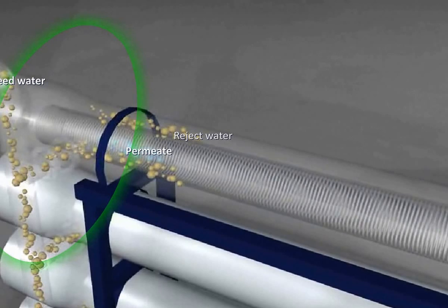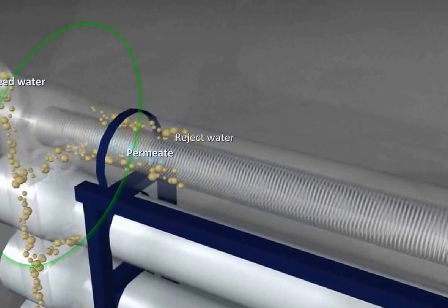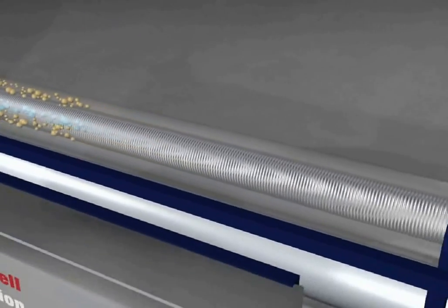The RO supply header distributes flow to each of the 5 RO pressure vessels. The pressure vessels have 2 flow paths which exit the other side of the vessel. Flow that has passed through the RO membrane is collected through a tube located in the center of the pressure vessel. This water is called permeate due to the fact that it is permeated or passed through the membrane. Permeate is collected from all of the pressure vessels.